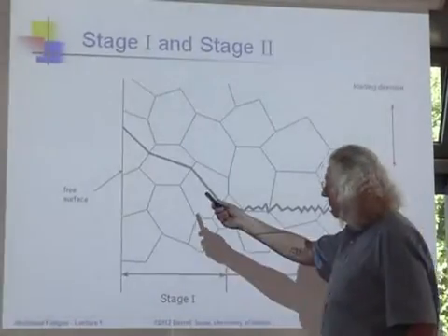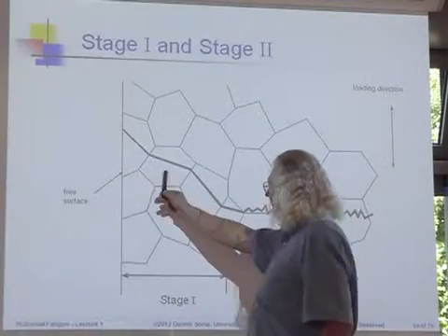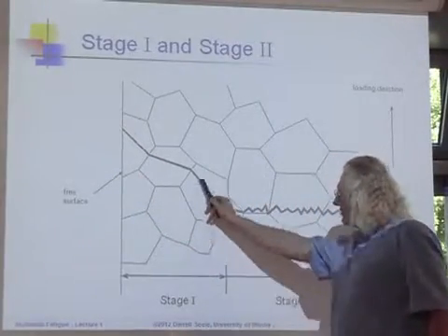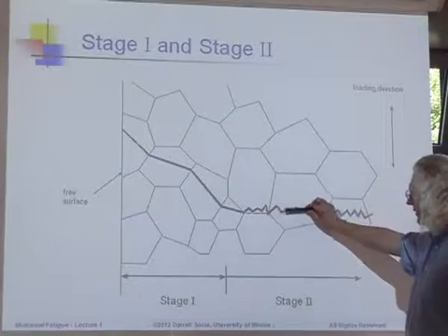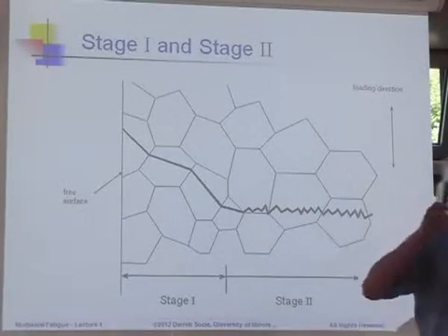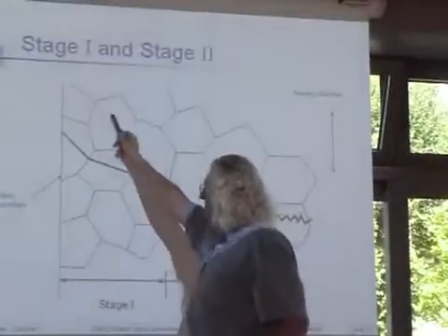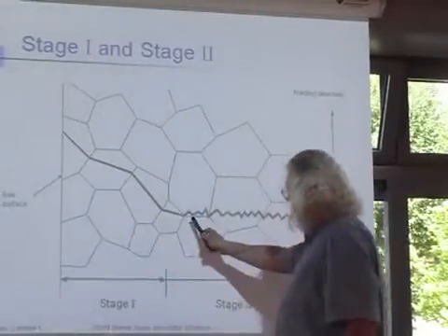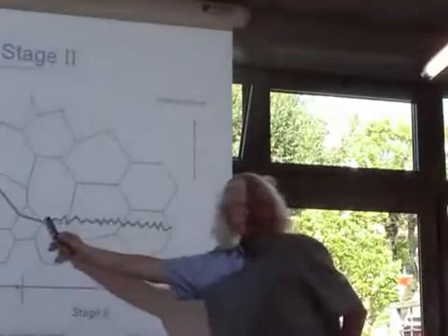And so now if we look at what happens, cracks do nucleate more or less in shear, and after they go through a few microstructure units, they always turn and grow perpendicular to the applied loads. The reason that you use the tension stress when you look at fatigue is because that's what you see. You don't see this part where maybe all the life is consumed, where it's growing in shear. What you see is this part, the bigger cracks. And the bigger cracks always grow perpendicular to the applied tension.